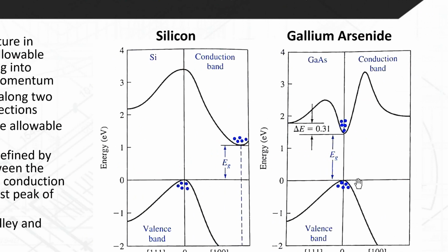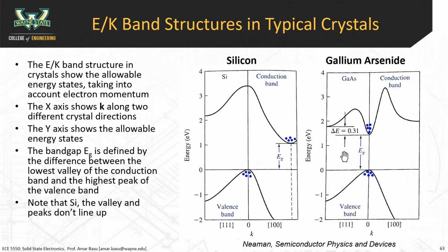Why the band structures line up like this has to do with the mathematics of the Schrödinger equation, but the result is very important. The difference between the two is very important. The fact that an electron only has to change energy, and doesn't have to change momentum, means that a recombination event, where an electron goes from the conduction to the valence band, can happen very, very quickly.